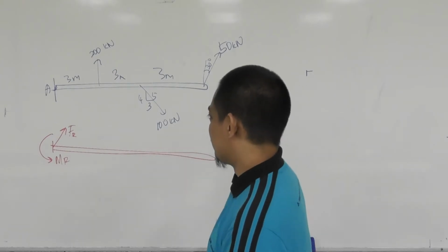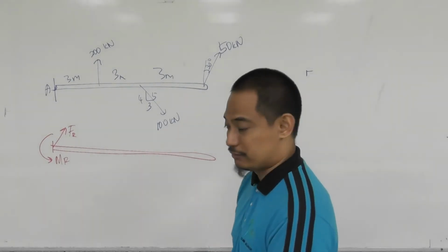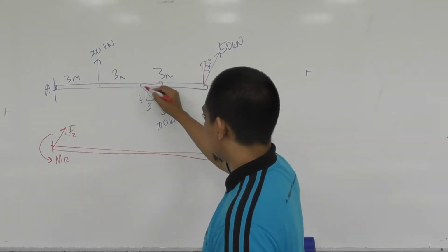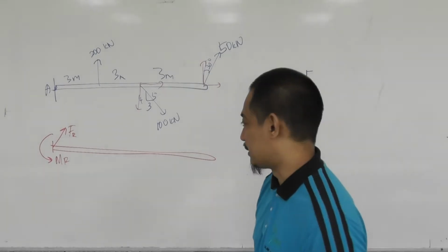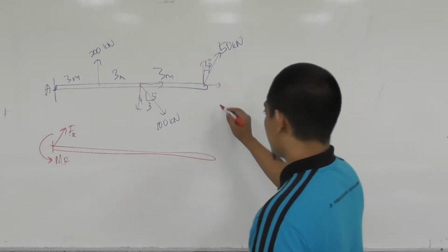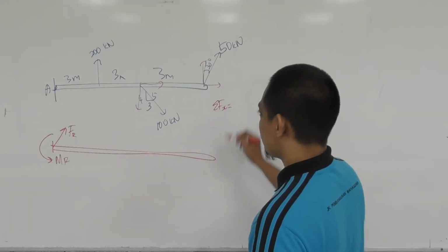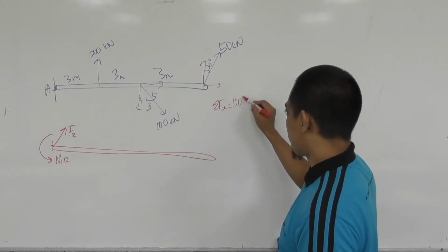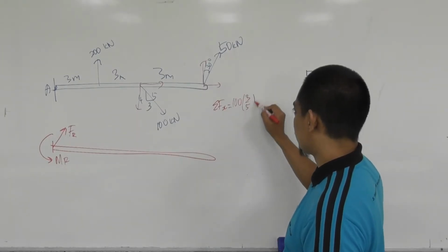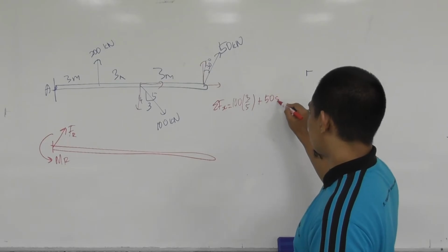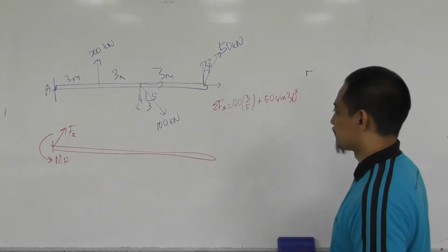Now, what you do is, basically if you have 2D, you have to resolve this, for example this one and this one, this one and this one, and then you just get the resultant there, right? So, in terms of the x component, summation of all Fx, this one is, we get 100 times 3/5, and then this one is plus 50 sine 30.